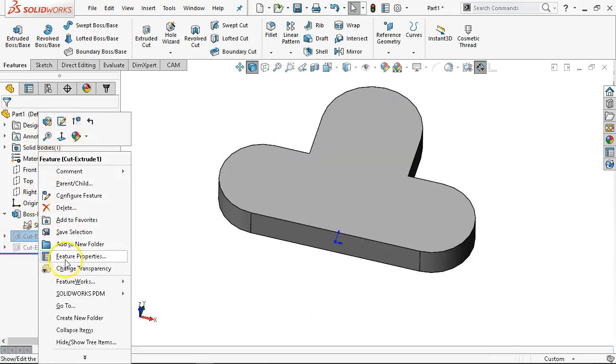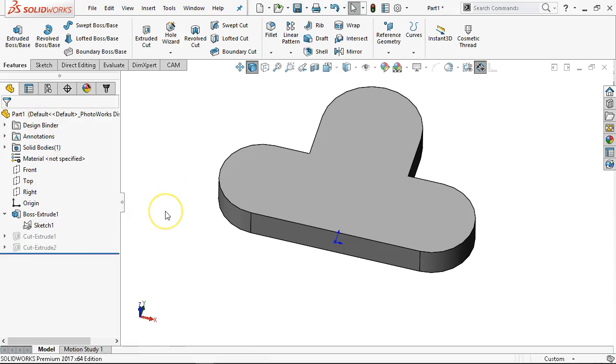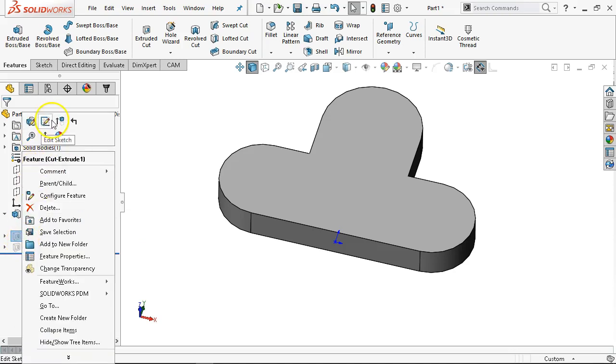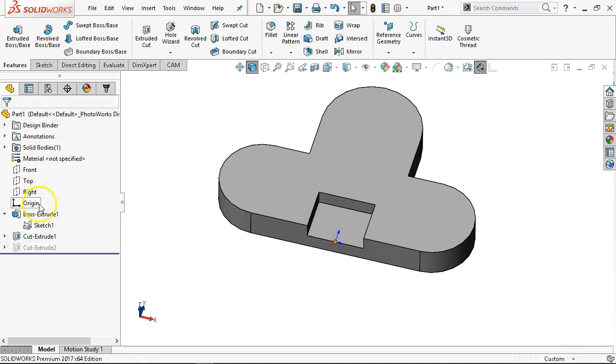And if I were to go through and try to do something with my suppressed items, well, they're not participating in hardly anything. Right, we can edit the sketch, I can unsuppress it, but we've lost a lot of that capability. All right, so I want to see it again. I go in and I tell it to unsuppress. It's back.